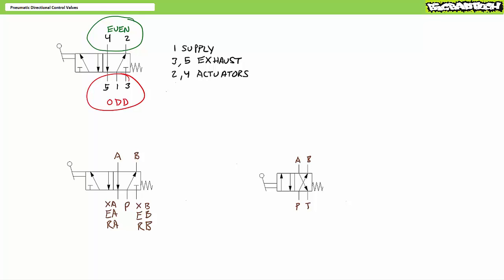As you'll soon learn, actuator speed control in a pneumatic system is a serious pain in contrast to a hydraulic system, principally because the power transfer medium of choice central to pneumatic systems, air, is compressible and occupies different volumes at different pressure and temperature conditions. This means actuator speed control via various flow control methods is a pretty involved task for pneumatic systems and often necessitates access to both upstream and downstream, i.e. pressure and exhaust, for independent actuator ports. Long story short, ports 3 and 5 might not be directly exhausted to the environment, and accessory components might be between the directional control valve and the actuator or exhaust.